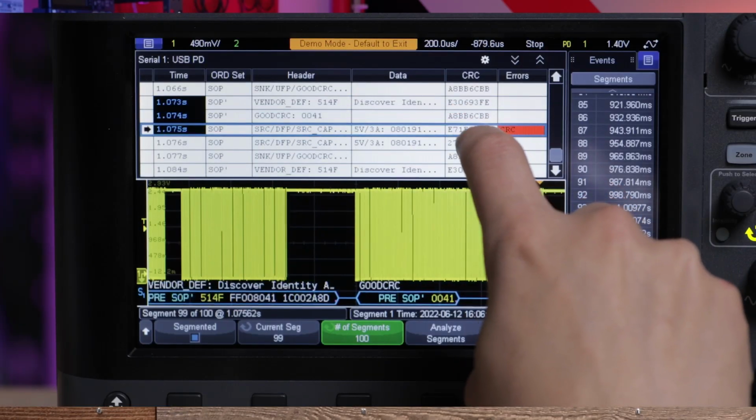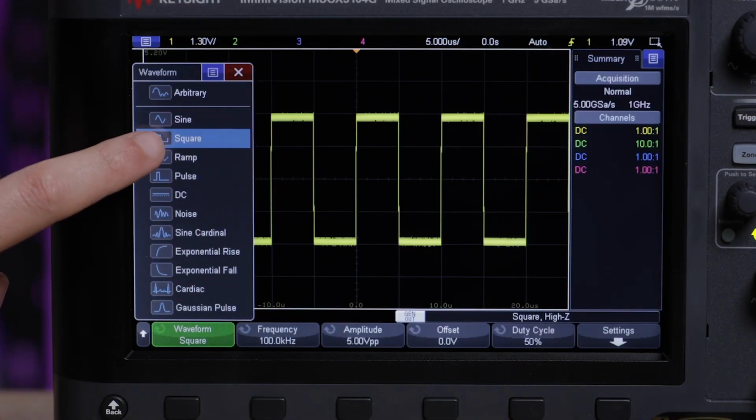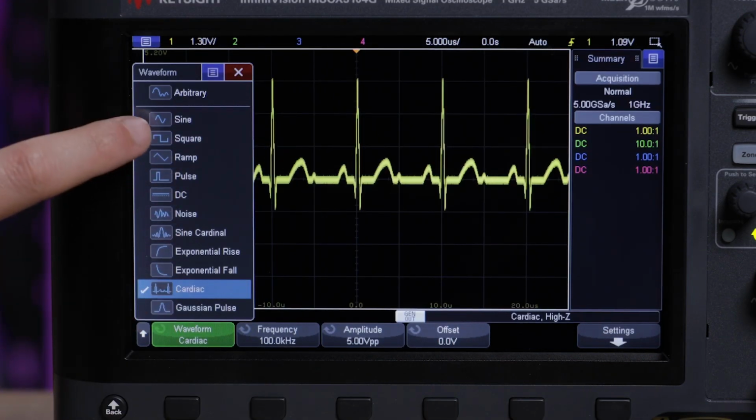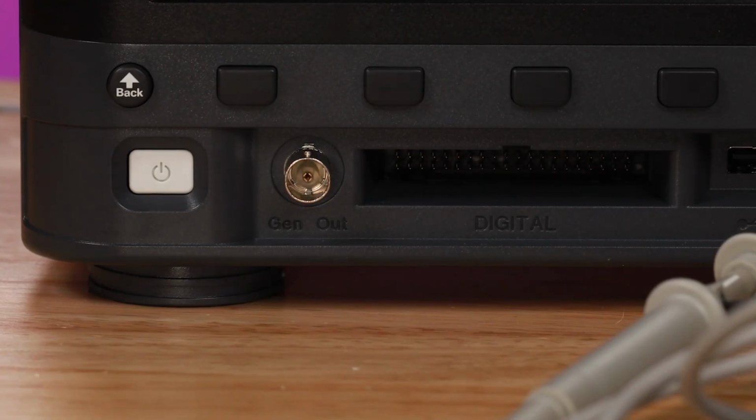Keysight's 3000GX series is more than an oscilloscope. You have, of course, the oscilloscope. You also have a protocol analyzer, frequency response analyzer, 20 megahertz function arbitrary waveform generator, 3-digit digital voltmeter, 8-digit counter and totalizer, and you can also add an additional 16 integrated digital channels to turn your oscilloscope into an MSO, a mixed signal oscilloscope.